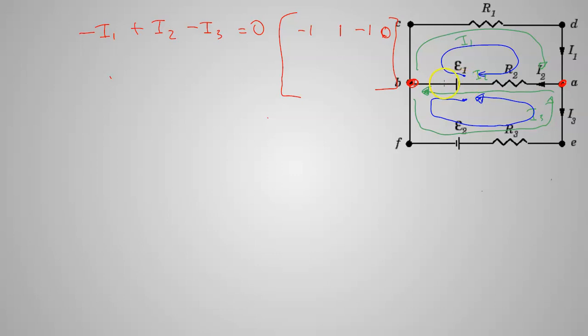It's voltage gain from here to there, right? But going backwards would be a drop. And if I go backwards across a resistor, that wouldn't be a drop, it'd be a gain. So you have to think about all the signs, and to avoid that, just go with the current as much as possible. But you could lay that out, and again, I don't know what the voltages are here, so I can't even really work it. But you know, getting it set up is kind of the hard part.